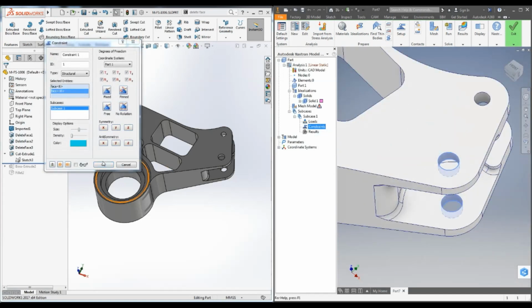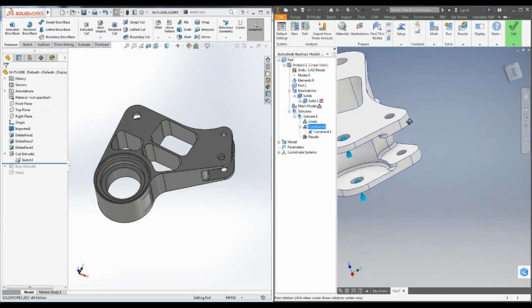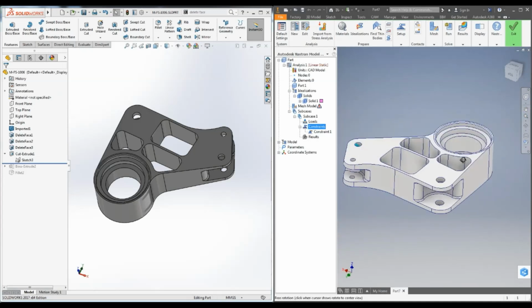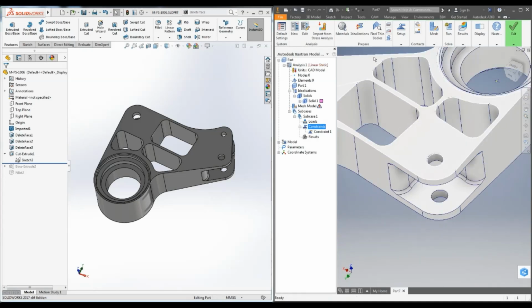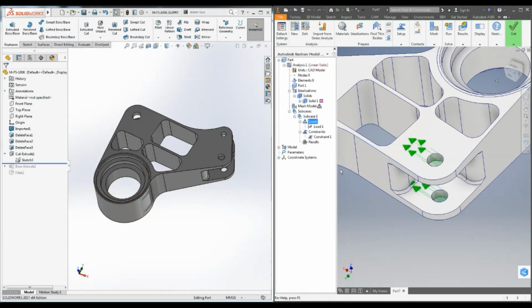From here, I can just proceed by putting in all the constraints needed to run this analysis. And then what we can do is add loads. If you want to run the analysis, obviously you need to add loads, right? So I added loads through edges. Basically, from that SolidWorks part, I can detect all the edges, all the spacing, faces. I can just reuse it.